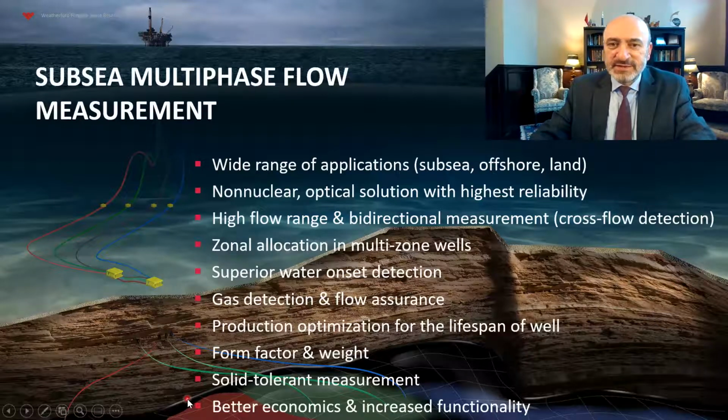So we believe that the integrated system provides better economics and also increased functionality. Once the optical flow meter is in the well, that means the fiber optic infrastructure is already available. That also helps us to enable other fiber-based technologies such as distributed temperature sensing, DTS, or distributed acoustic sensing, DAS.